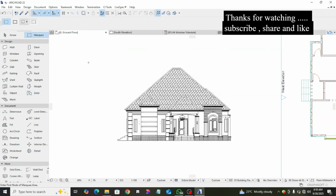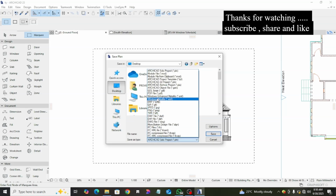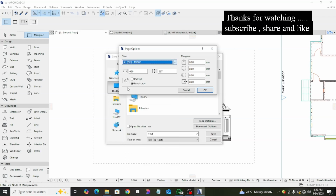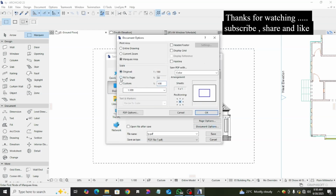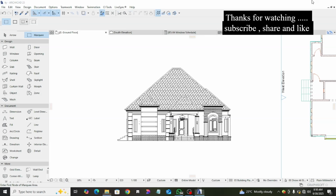Or you add your line, use mark, save as, desktop, click on this, look for PDF, save it as PDF. This is PDF. Do your settings, A3, 0 0 0 0. Okay, the next option here, original page, color, black and white, everything is okay. Okay, I'll save it.